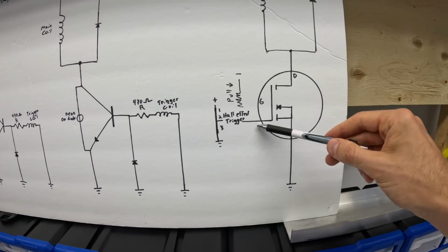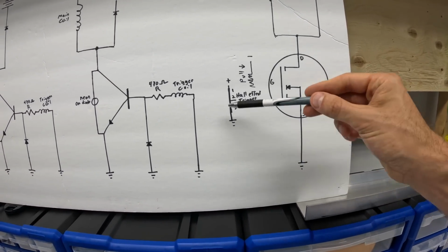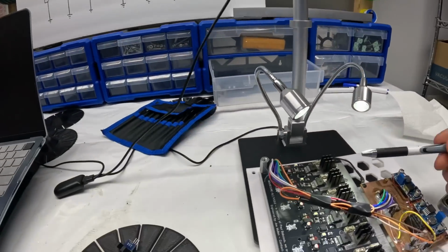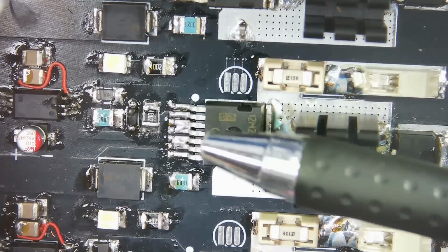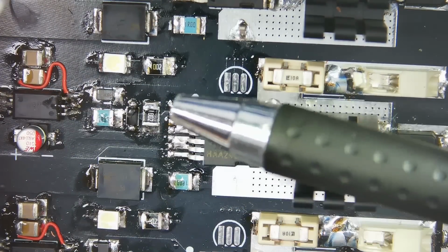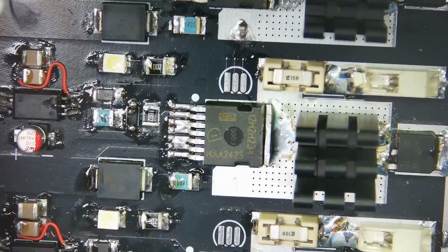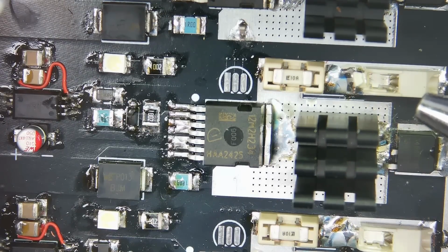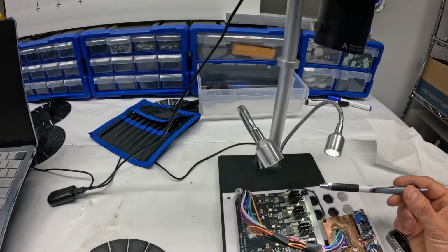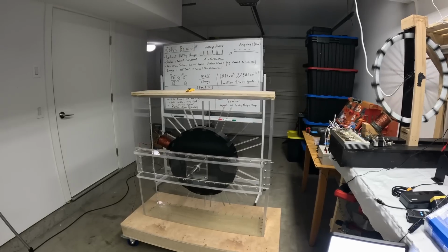This is a better diagram of it. This one I wrote as a Hall effect trigger. You could use a Hall effect as well, but basically this triggering portion is this driver down here with the optic sensor driving this N-channel MOSFET, and then this main coil up here is now being connected to this section right here. You guys can see that pen there. So that coil goes in there, there's a fuse protecting it, and when this MOSFET is driven, it completes the circuit. And the same thing, this drives the coil on this bigger machine and makes the rotor move.